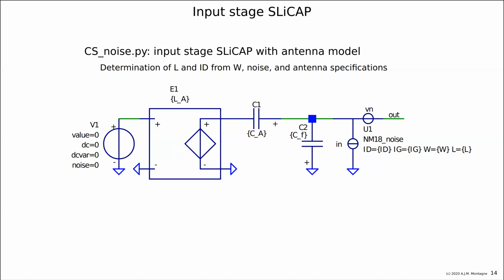Then you cross the intersection point of C1 and C2, and it splits in two correlated sources, and you have to account basically for both sources, which means that effectively Vn is multiplied with a factor that is set by 1 plus the ratio of the capacitors.